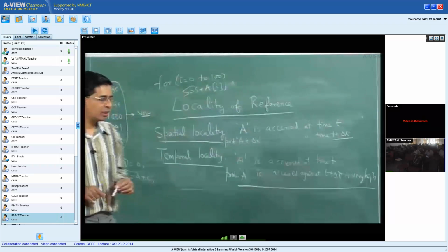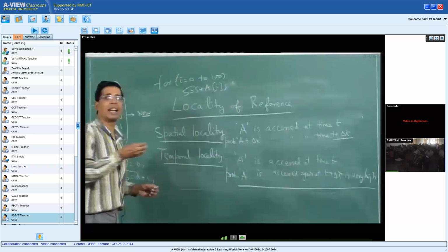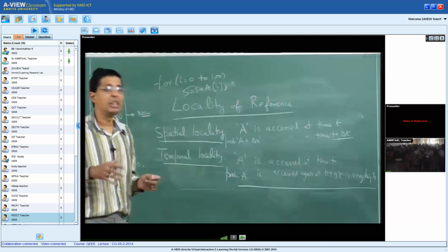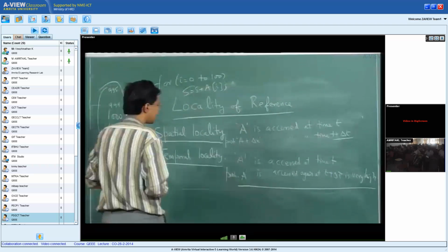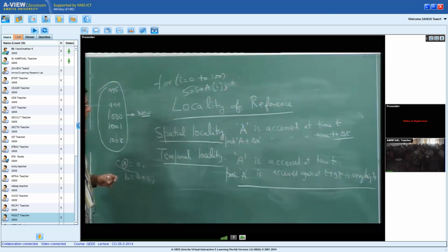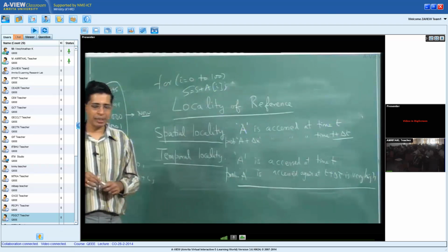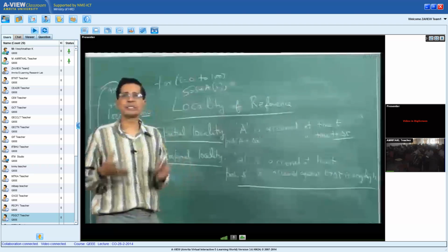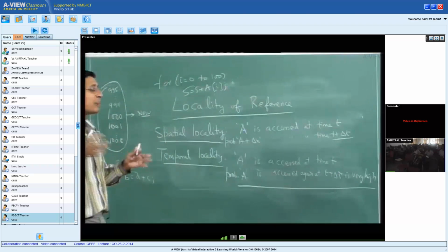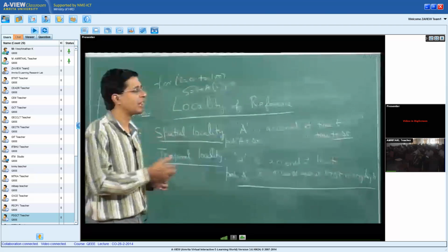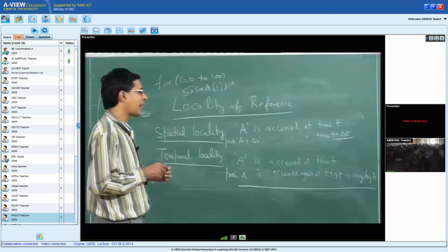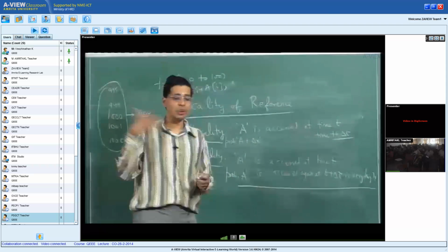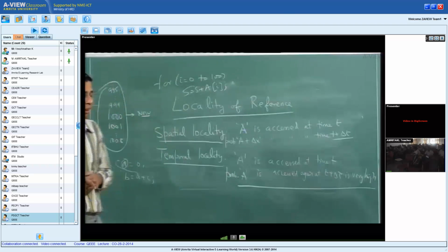So this also is taken as an input in the development of a cache architecture. There are two important things that we need to keep in mind when we are building the cache architecture. Part number one is that 10% of the code is executed 90% of the time, and so it makes sense to move that 10% from the RAM into the cache, and if I do that successfully, then it is going to be very beneficial. It can give us a large performance improvement because it makes the processor almost independent of the memory for the majority of the execution of the program.